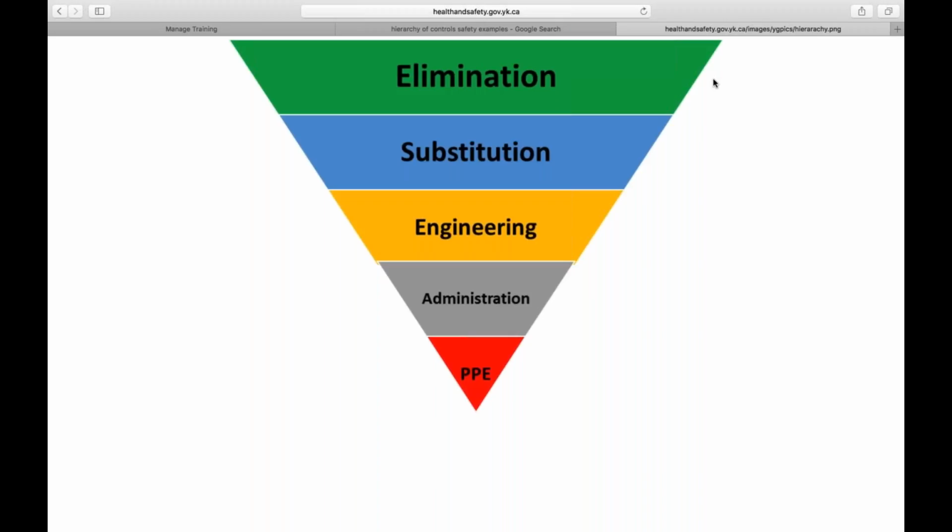Well, we have to identify the site and the layout. Where's the work site? What's the layout of the site? The scope of work that we're going to do. Are we doing any excavations? Any trenching? Any hot work? Any confined space work? Any work around energized utility lines, pipelines under pressure? All that has to be taken into consideration.